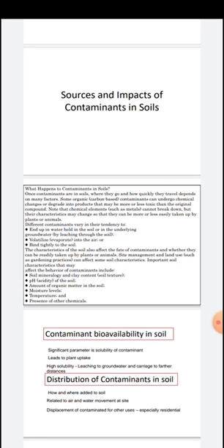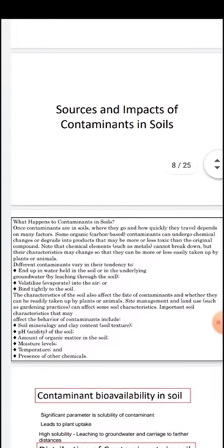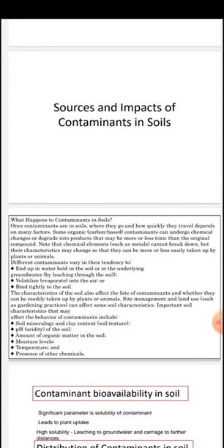On the other hand, if the soil is having a texture which is very dense, the voids are very narrow, and which is hindering the movement of the water through the pores, in that case the mobility of the contaminant is restricted. So in most cases the contaminant will be retained in the soil. So based on that, we will again look into the different parameters and aspects which are responsible for this kind of behavior of that contaminant in our soils and in our groundwaters.